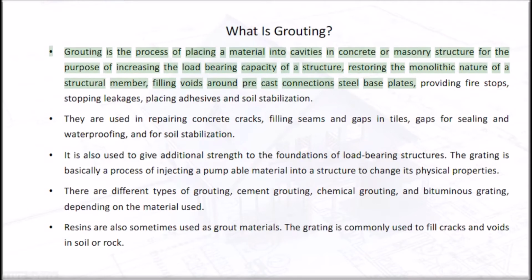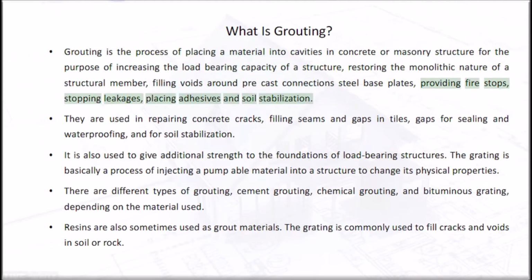Grouting is the process of placing a material into cavities in concrete or masonry structure for the purpose of increasing the load-bearing capacity of a structure, restoring the monolithic nature of a structural member, filling voids around precast connection steel base plates, providing fire stops, stopping leakages, placing adhesives and soil stabilization.